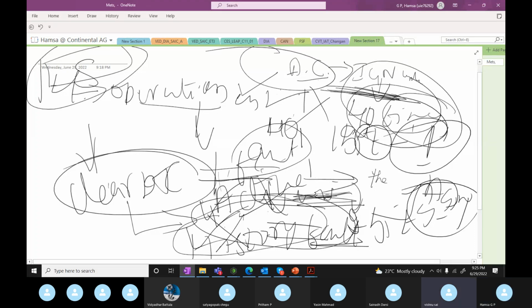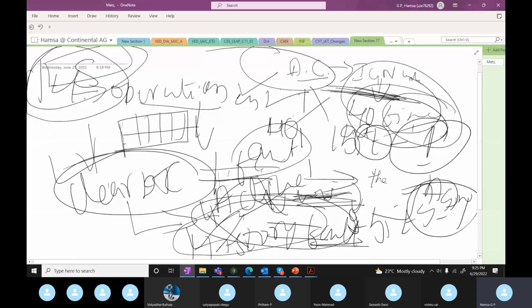Clear? Yeah, clear. This is the real scenario that happens with the aging counter. But when you take your car to the service station, or as a tester, you have a service called service 14 which clears the DTCs. When we say clear the DTCs, it means that wherever the DTCs are stored in memory, that memory is cleared. This memory is usually the EEPROM, so it will clear this memory completely.